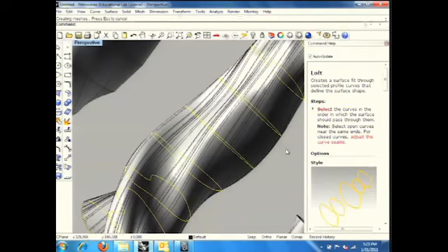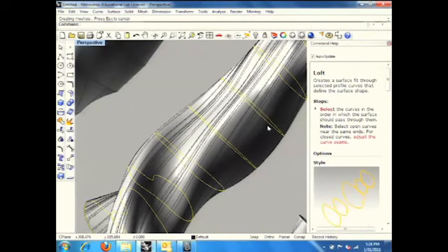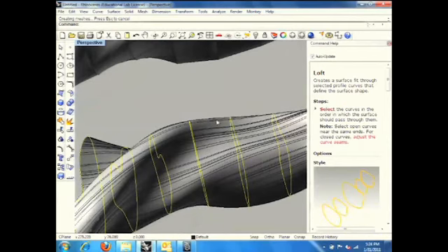Actually, in the real construction of a skyscraper, you can think about this as a glazing system. And the glazing system is always made up of many, many panels, right? The panel is always flat. It's a 1 degree surface. It will be extremely expensive if you want to do a 3-dimension curved panel. Maybe you can see that in aircraft or car, but nobody really does that in a building. It's super expensive. That makes sense?